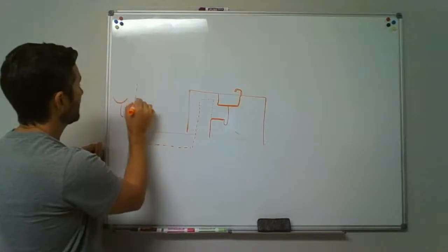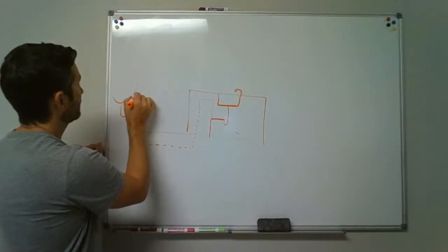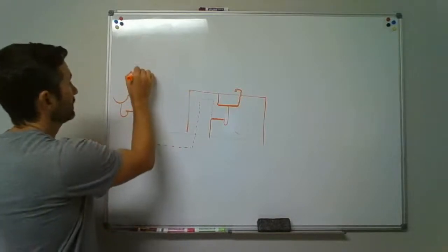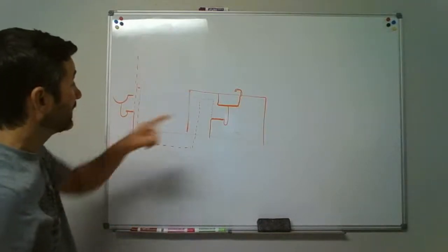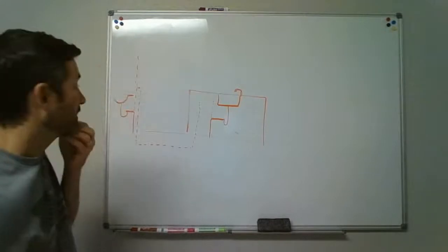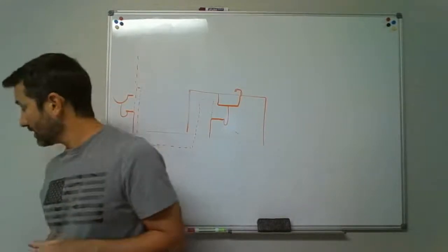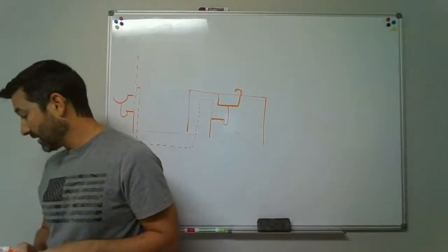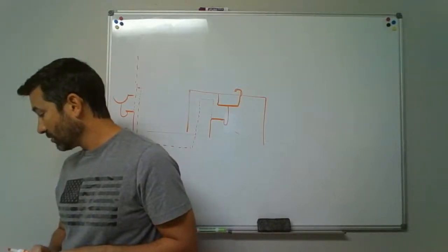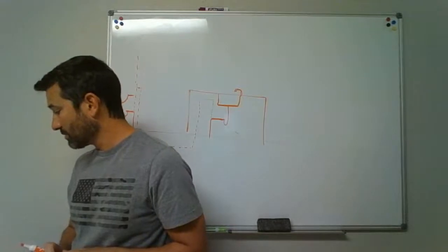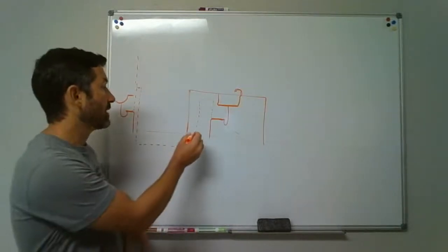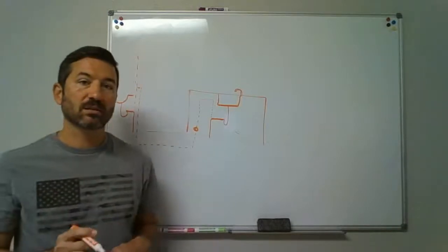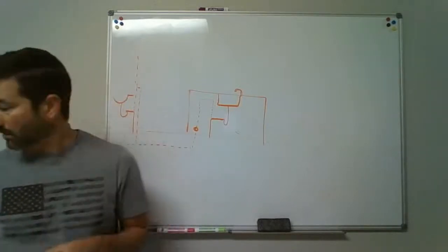And remember, when you tie to sinks, you're going to be higher than their flood level rims, 6 inches. And you can connect that vent back to there. It should be talking about putting cleanouts on those lines. Cleanouts should be provided on the island fixture vent to be permitted routing located below the flood level on the fixture. Routing in both directions should be permitted through a cleanout. Yeah, you've got to have that. You've got to have cleanouts because you can get stuff stuck in there.